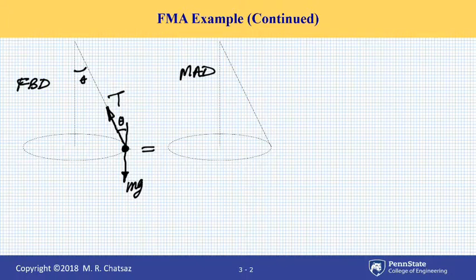On the other side, I will show components of acceleration. Due to the nature of geometry of the situation, I choose to go with the NT coordinate system. So normal acceleration is pointing towards center of rotation, therefore I have m a_n in this direction, and in general tangential acceleration is tangent to the circle, m a_t. Now let's also show the vertical direction by y-axis. There is no acceleration in y or vertical direction.